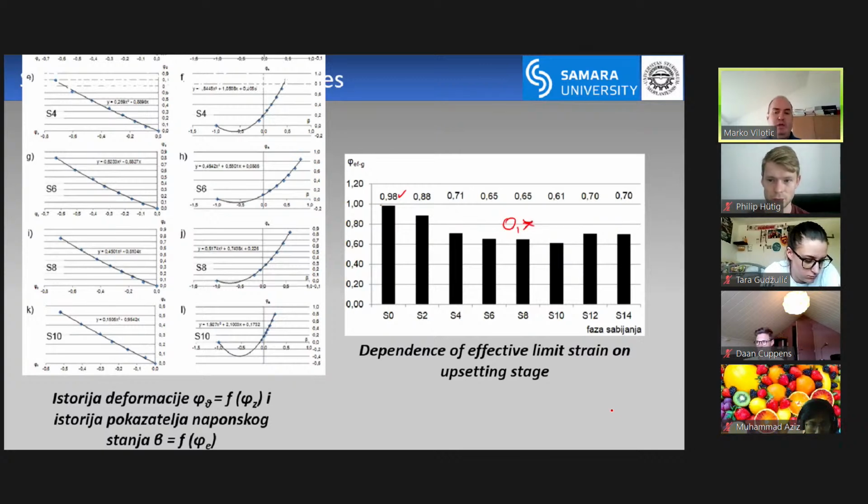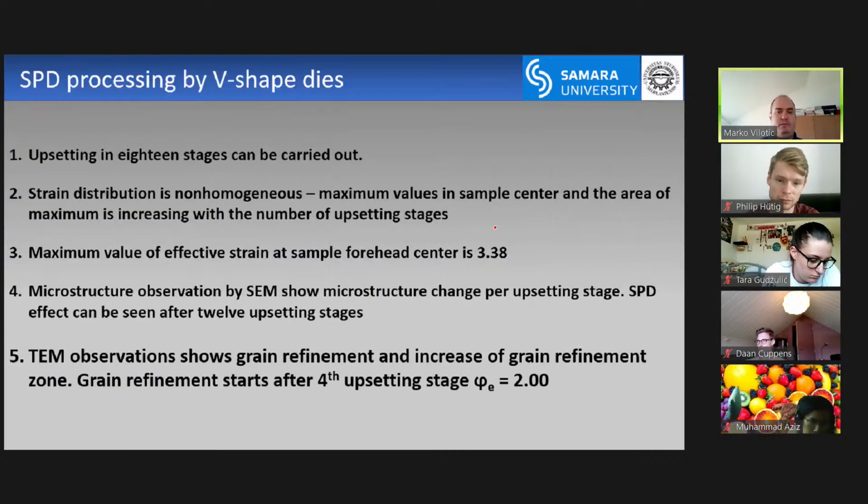So some people say, yeah, we lose some formability, some ability to be plastically deformed, but still this result is good. I would say, I'm just paraphrasing, just imagining things, that in conventional metal forming the results would be somewhere in this range. I'm not sure if I'm right. So this is still good. It means we get improvement in terms of microhardness, ultimate tensile strength, and yield stress, but we lose some of the ability of plastic deformation. So let me give some conclusions about this method.